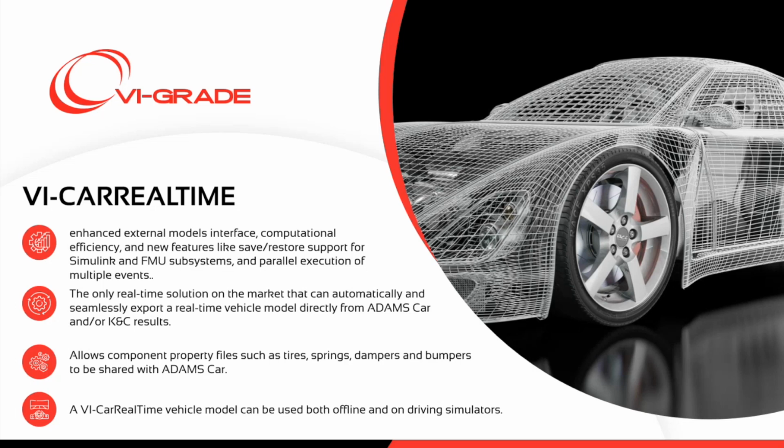This is the scenario where we step in with VI-CarRealTime. Our goal is to make VI-CarRealTime the best platform to achieve integration between vehicle design and controls design. VI-CarRealTime allows to connect to external component model, for example, with MATLAB Simulink, and it also easily integrates with the FMU subsystem, functional mockup unit subsystem. This integration capability gives to the user the flexibility to bring complex control algorithms in or other generic external components actually directly into the vehicle real-time simulation provided by VI-CarRealTime.